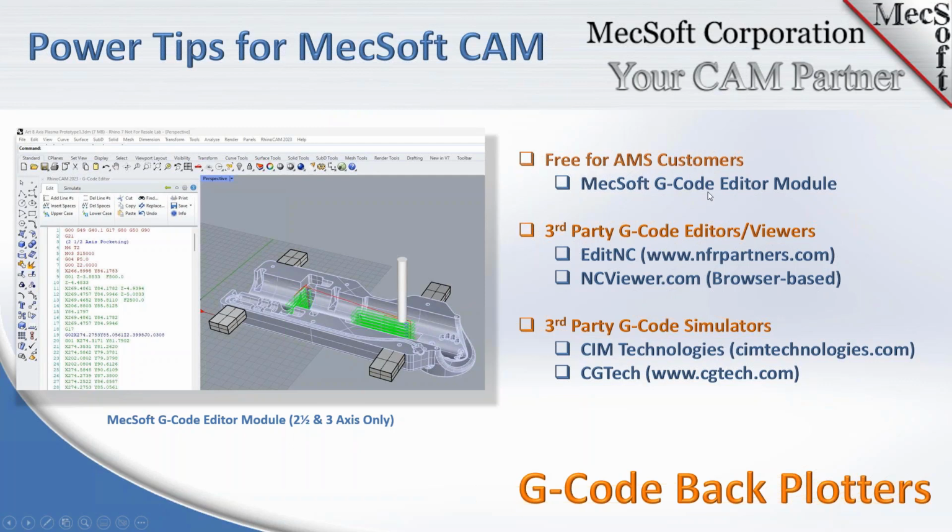If you're an AMS customer, you'll get the G code module along with your CAM modules. If you want to use third-party editors and viewers, we have some listed here, from free to medium range, and high end down here. Basically, these are reading the G code coordinates and the codes in your G code file and graphically showing you what they mean on your computer before you send it to the plotter. You can see your G code graphically, and a lot of times errors will blare out at you. You say, oh, that's not going to work, these arcs are all over the place, or things like that. Or you can go through it line by line and look at where the tool is on that line and what it's doing. So they're very good for helping you debug your G code.